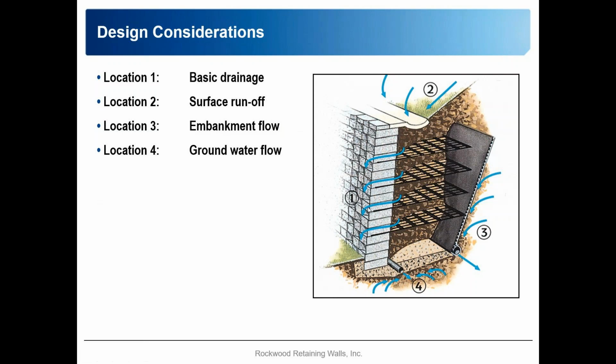If we see that, we want to stop what we're doing and let the engineer of record, if it's on a commercial job, take notice of it. But it's really pretty simple. It's just a kind of board with a plastic material in here, with geosynthetic geotextile on the outside of it. It captures this water, brings it down to a drain and takes it out.